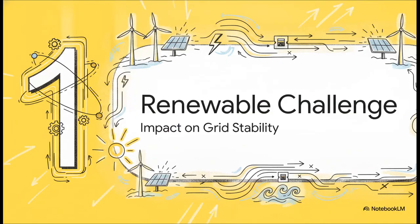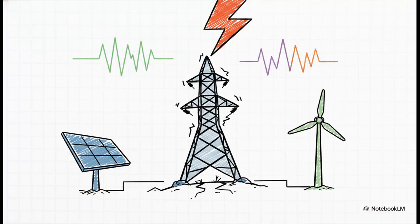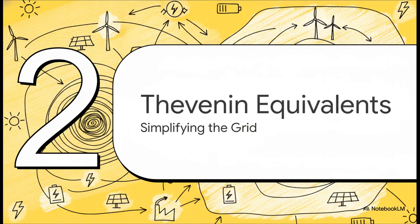All right, part one, the renewable grid challenge. The massive influx of renewables isn't just an energy shift, it's a dynamic shift. Because solar and wind use power converters, they offer very limited inertial support. Without that heavy spinning mass to basically push back against a grid fault, our frequency, voltage, and transient stability are all highly compromised.